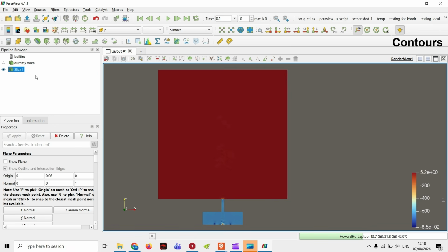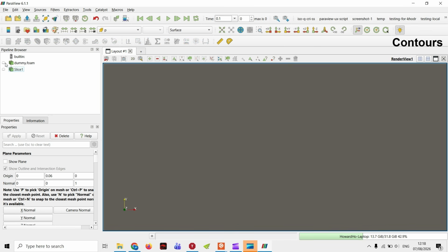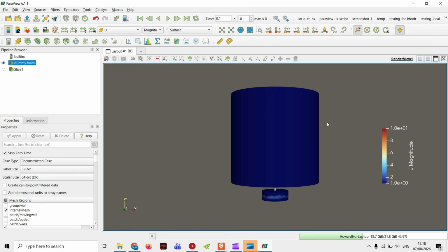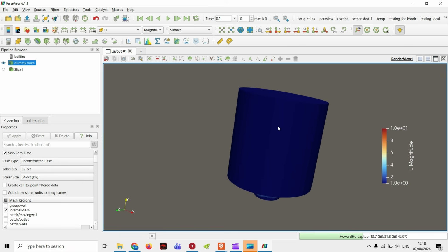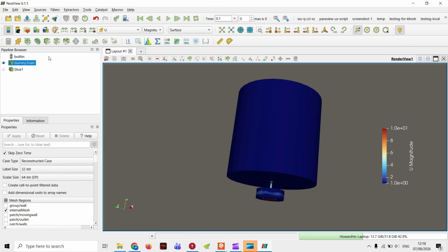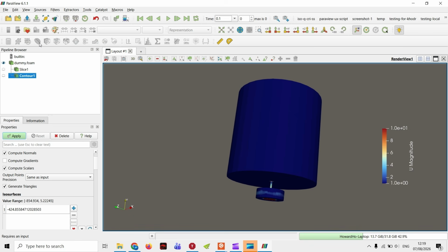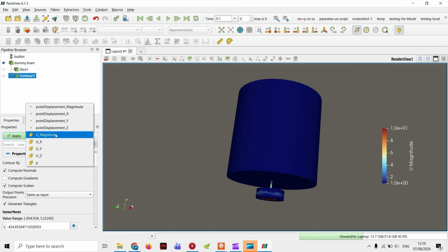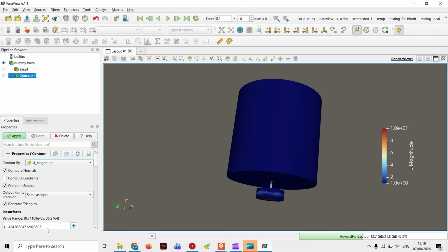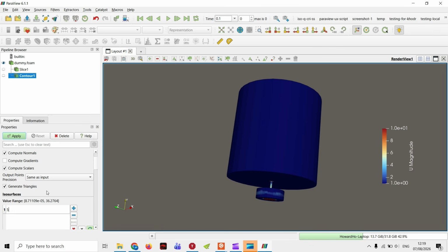Now, another thing we're also going to do is contours. Now, we're going to hide this slice and then bring back up our original 3D geometry or 3D fill and click a threshold button, or sorry, contour. Oh yeah, they've changed the name to generate ISO lines or ISO surface. Same thing. Let's say I want to plot the velocity magnitude contour for 5 meter per second.